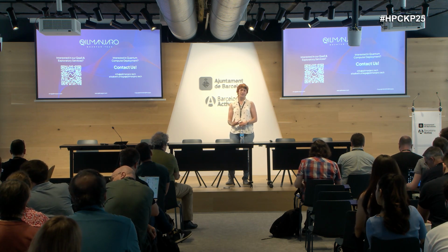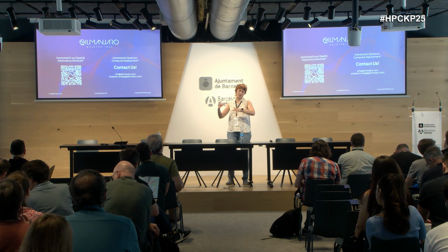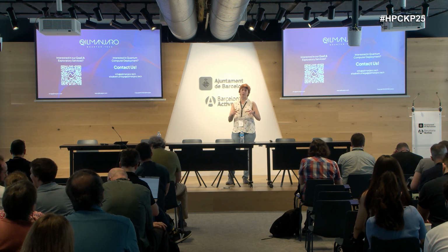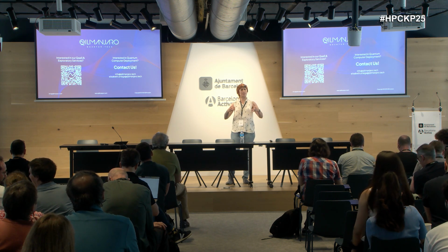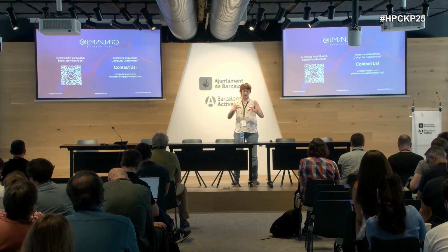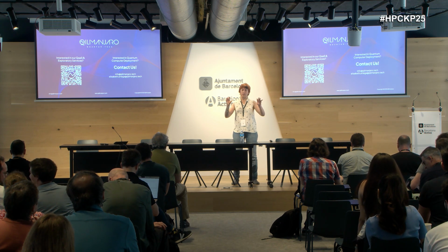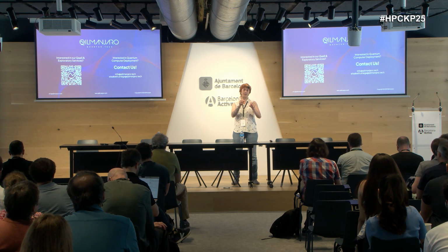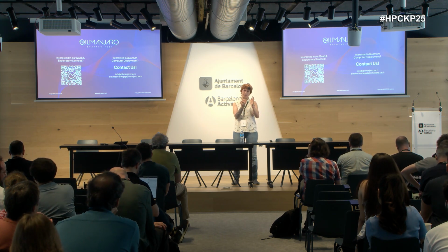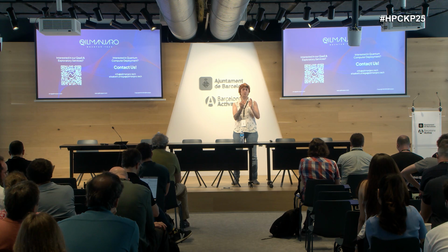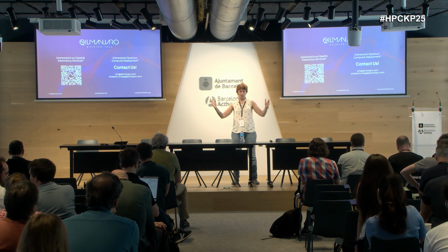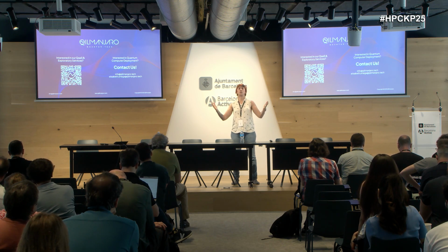It's like that. The difference is not in pure analog and pure digital; the coherence times are different. In the chip that we are doing, which is a fluxonium, I can be technical with that. The difference is with the transmon chip, which is the one used for mostly all the digital ones. The one that we use has an inductance that shields the system a little bit, so it makes the system less prone to errors and less affected. That increases the coherence time. The longer the coherence time we have, the longer the circuits or the simulations can be.